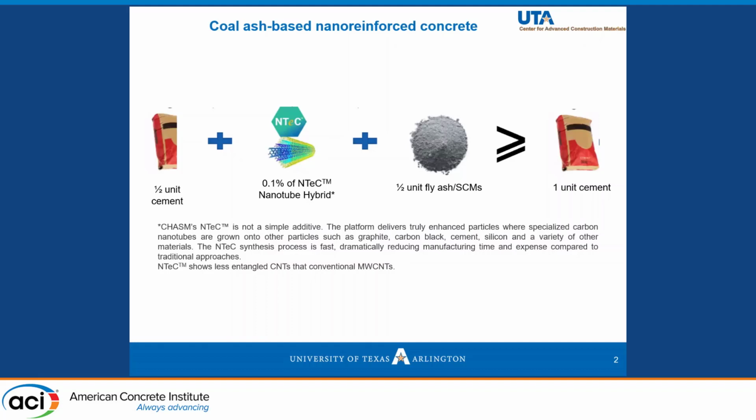Some people mostly use amounts of fly ash varying from 15 to 25%, and that's also recommended by ACI. Though we all know that fly ash, and in general coal ash, is one of the largest industrial waste products, and can be a great and very cost-effective solution in reducing the content of clinker in concrete.